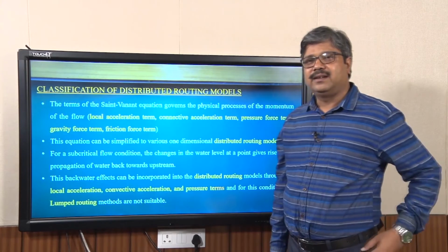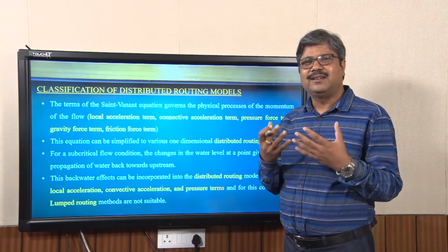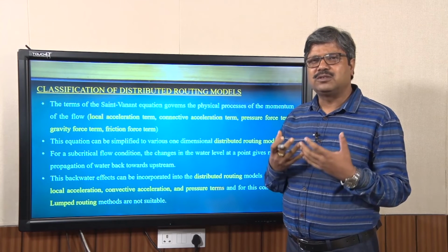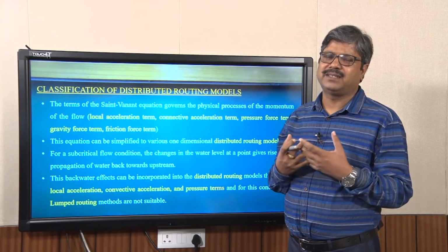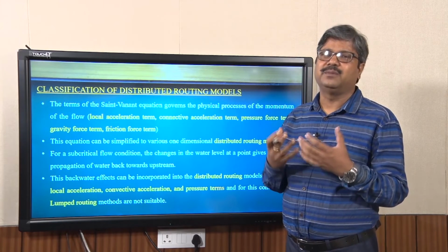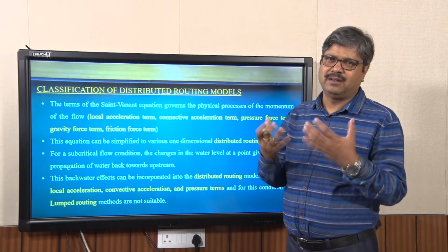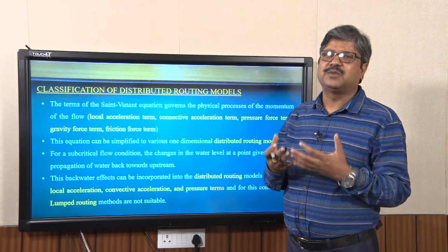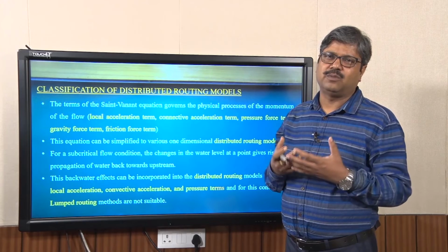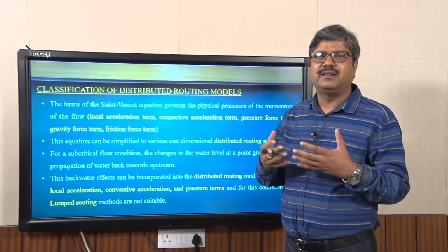As I discussed, the Saint-Venant equations are nonlinear partial differential equations, but solving them is not that difficult. Most of the time the difficulty is giving appropriate river geometry. As I said, the river is quite dynamic: low flow, bankfull discharge, 10-year return period flow or 100-year return period flow all differ.